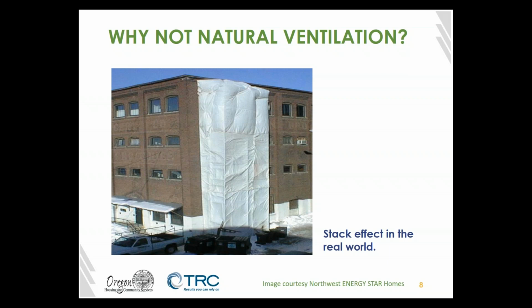But what about those middle floors? Those middle floors don't get much of a stack effect. And once again, you have stale air just sitting in those homes, sitting in those apartments. And that's problematic to those that live there. And even the stack effect can get shut down a little bit if you have a really tight envelope or if you have great compartmentalization going on within the building.